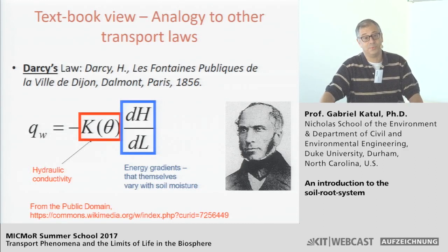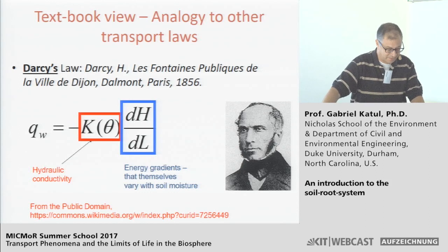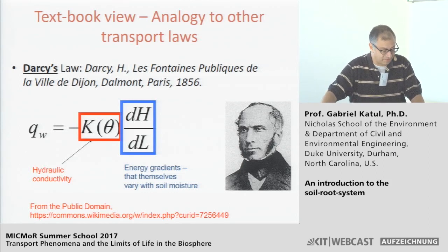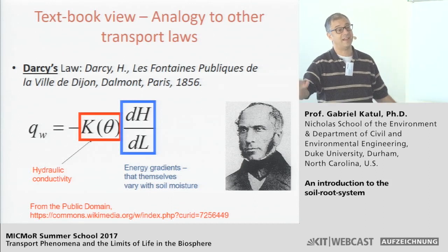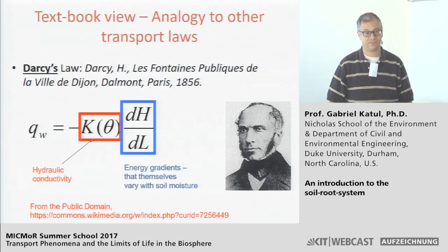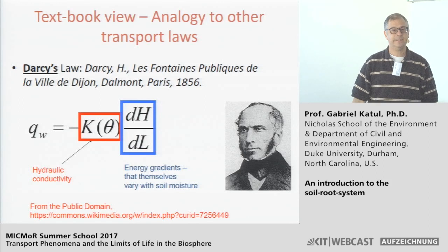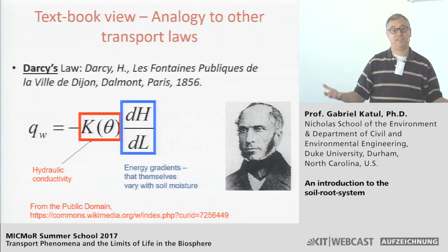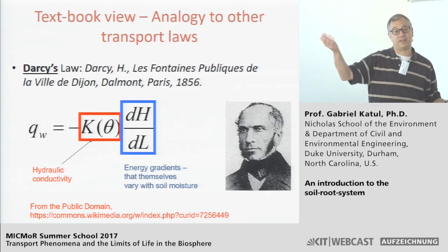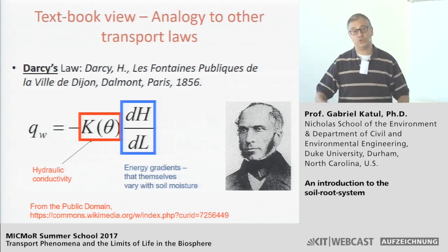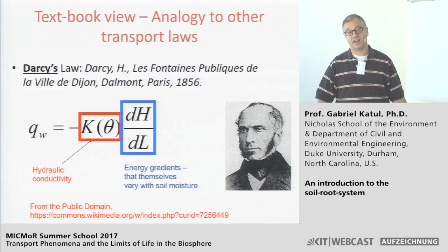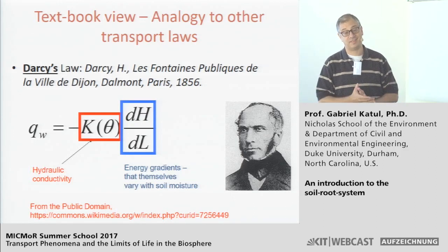Coriolis, who you probably have heard of, yeah. Bazin, who was also working with Darcy at the time. Bélanger, who worked on the hydraulic jump, basically. So the Bélanger equation is very famous. It was the first time it was discovered that if you go from supercritical flow to subcritical flow, you do that through a non-gradual way, through a hydraulic jump that produces a lot of turbulence that dissipates excess energy.